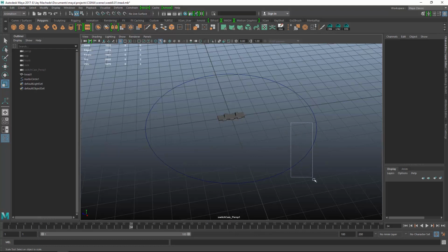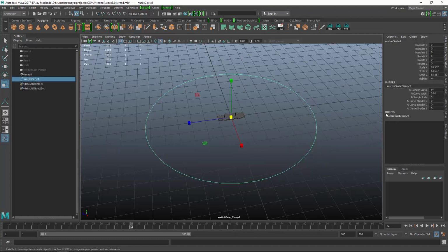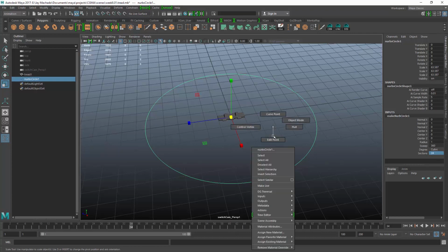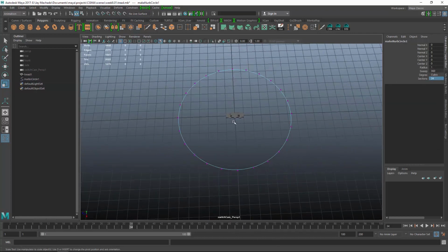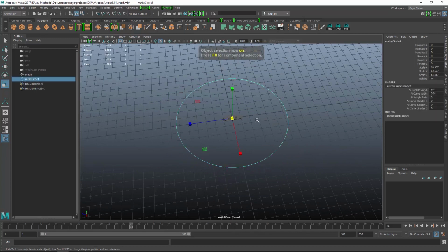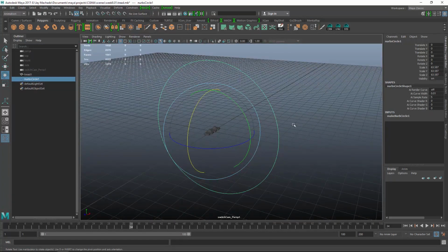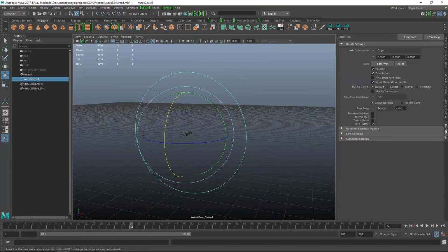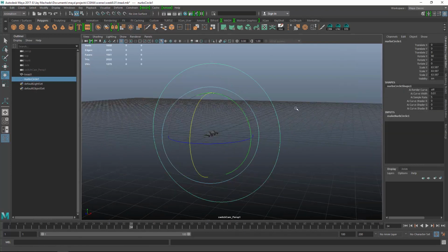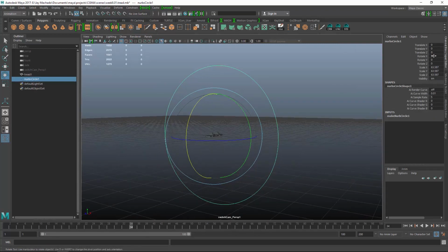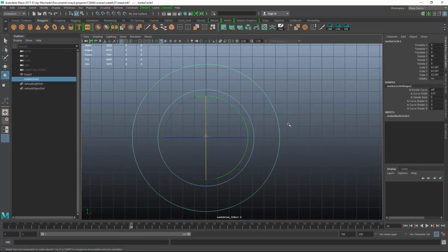So I'm going to grab this NURBS circle again, and then over here under inputs, you see make NURBS circle 1. I'm going to change the sections to 24. And now you can see if we look at the control vertices that we have a lot more to play with. So first things first, I'm going to actually rotate this, and you see I have a snap on my rotate right now. That's just in tool settings, step snap relative. I have it set to 45-degree angle. Doesn't really matter, as long as this is a vertical 90-degree angle.